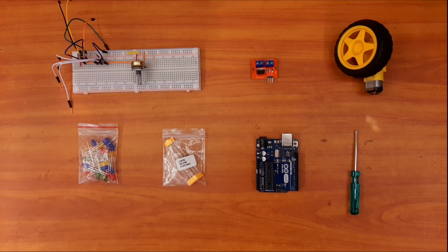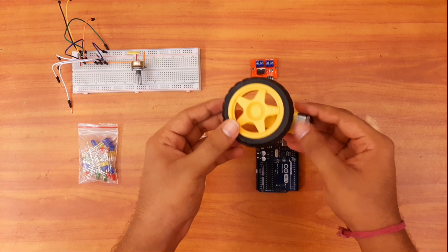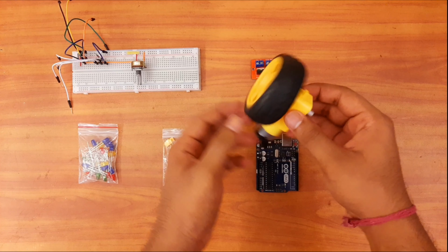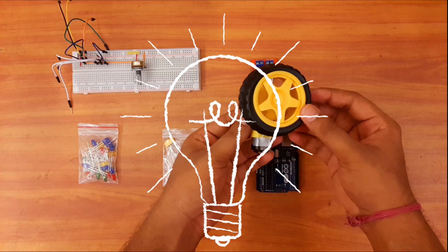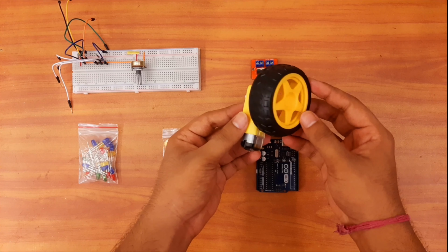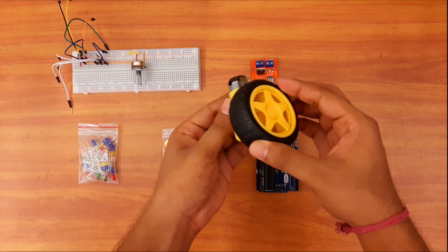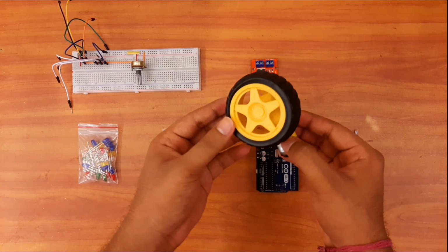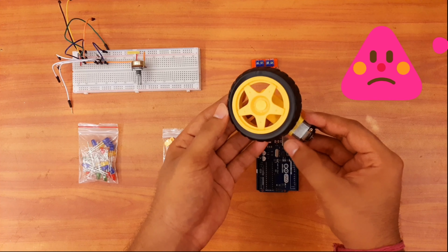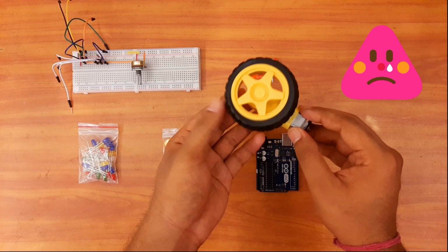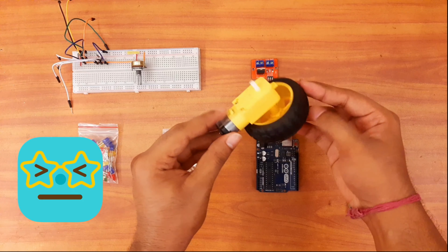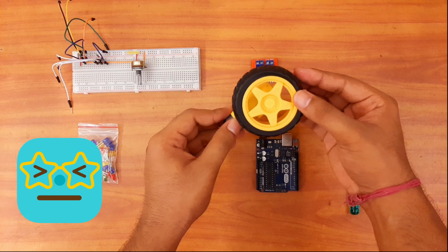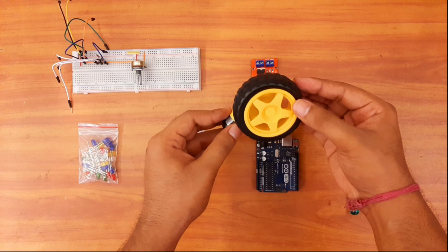Before entering into PWM, I would like to ask you a simple question. Suppose I ask you to change the speed of this motor with the help of a battery. The first thing that will come to your mind is to add a rheostat to the battery, vary the resistance, and thereby control the speed of this motor. But if you notice carefully, there is a great loss in the resistance that you are using. The second problem is that you cannot control the speed of this motor using Arduino or any other electronic circuit with the rheostat concept.